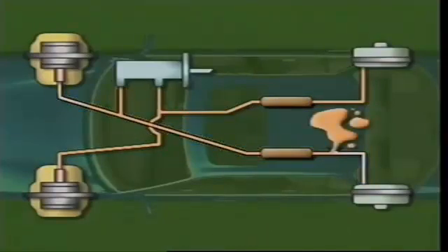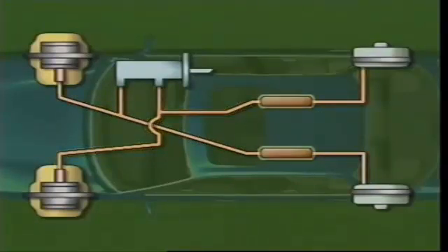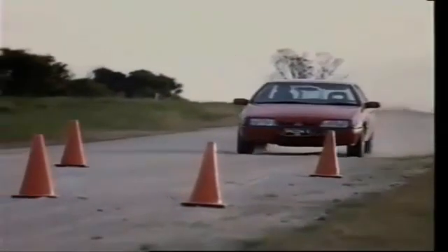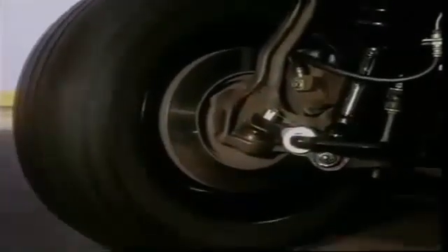If one system fails, a 50% braking capability is left in the other system. Dual proportioning valves maintain optimum braking in each system. A system that partially failed would cause severe braking pull on a vehicle's suspension, so suspension geometry is usually revised to counter this.